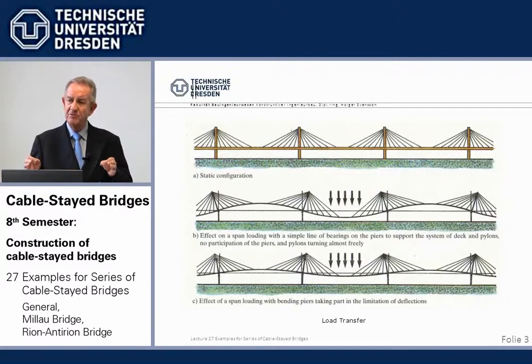The one problem is how to stabilize the tower tip, because there are no hold-down backstay cables. And the second is, because of their increased length, how to cater for the changes in lengths in the beam due to temperature, shrinkage and creep and so on.